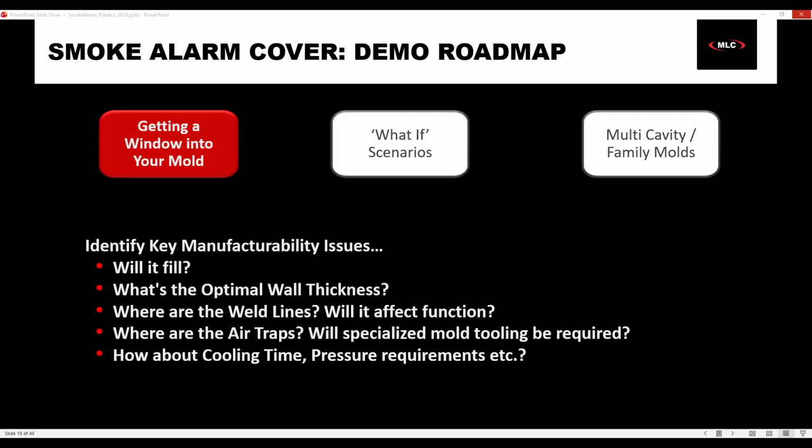I think the other thing I was looking at was under the units. So here is where this is pulled in from the material. I know you can't see some of this, but melt temperature, mold temperature. One thing I wanted to point out here is we have an injection pressure limit that we've set to 100. We're going to run into that later. So that is a limit we have set. We'll be able to see if something has hit 100, we know that it may have exceeded that, and we know that we need to get that pressure down. So again, some of this information you can enter based off of your own equipment. Some of it's pulling in from your materials.